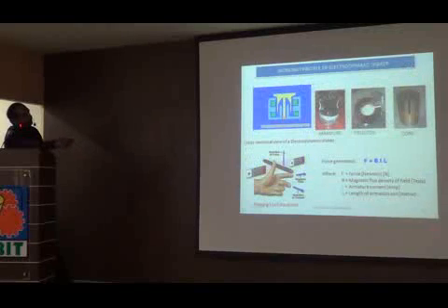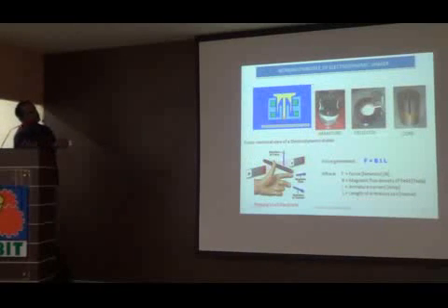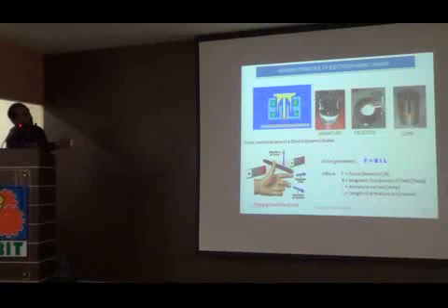Yes, I have shown you the working principle of the electrodynamic shaker. Let me show the full shaker and how it looks. If you see the cross section, it's something like this. This yellow part is like a conductor, placed in a magnetic circuit. This blue is the magnetic circuit, or we call it the body. It is put in this narrow zone between the center pole and the outer body, and you generate the flux below using these green things called field coils.